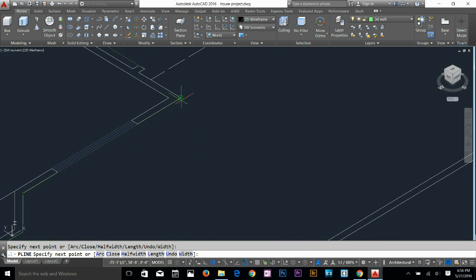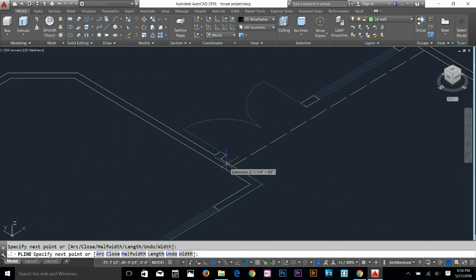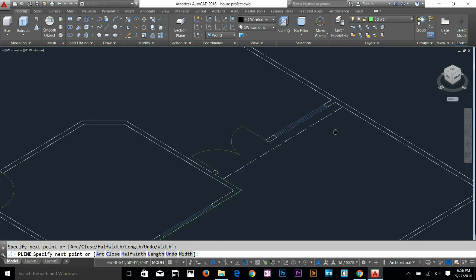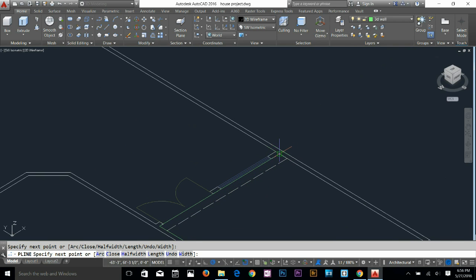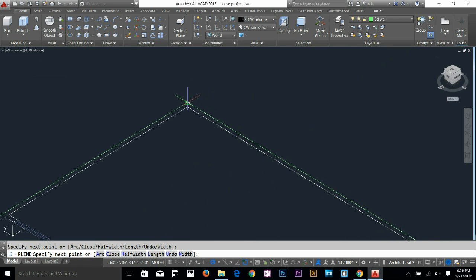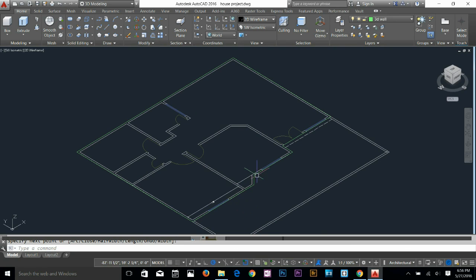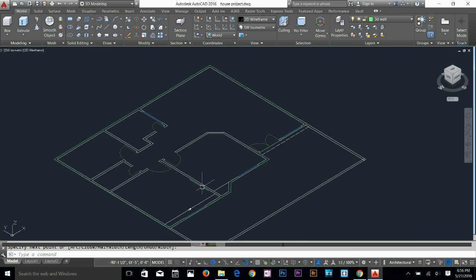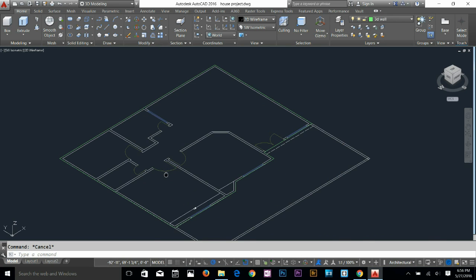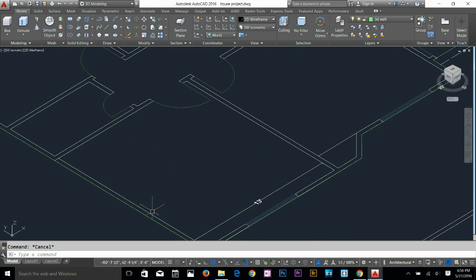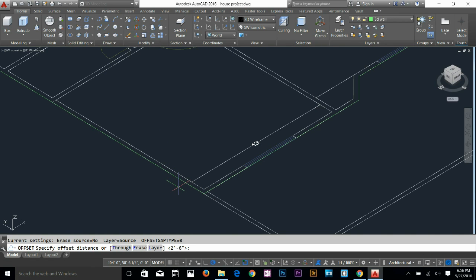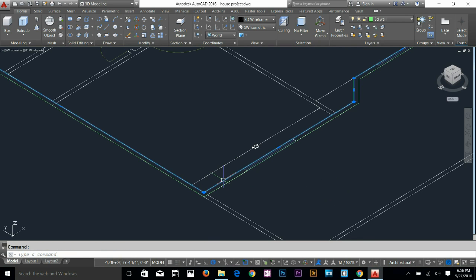This is just to make sure that it's a basic tutorial, so this is gonna give you a good idea of how you can make a 3D model. This is not an advanced tutorial. If you wanna know the advanced tutorial in which I make every single thing and explain a few commands as well, I'll drop a link in the description below. You can check that out. I've got a full tutorial of 3 hours making a 3D model on this same channel. Okay, so I'm just gonna offset about 4.5 inch, select from this point and just drop it there. So I've got 2 polylines now.